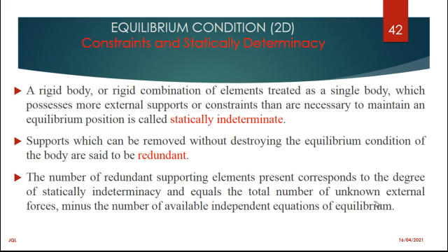The number of redundant supporting elements present corresponds to the degree of statically indeterminacy and equals the total number of unknown external forces minus the number of available independent equations of equilibrium.